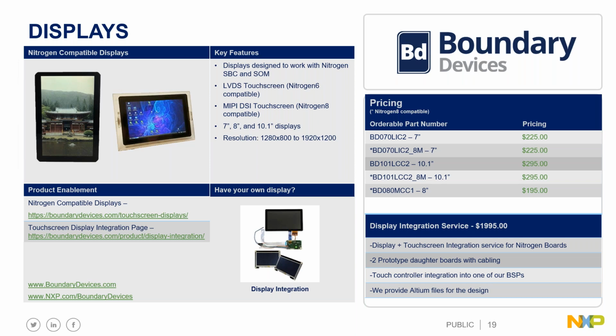We also have a display integration package where customers can select their own display, whatever display they want to use, and they would send that to us and we would integrate it. So we would do the timings, the U-Boot changes, the kernel changes, as well as integrate the touch drivers into the customer's OS of choice.